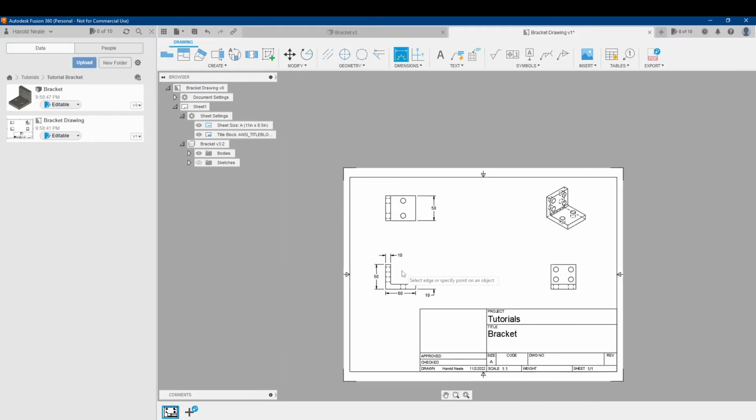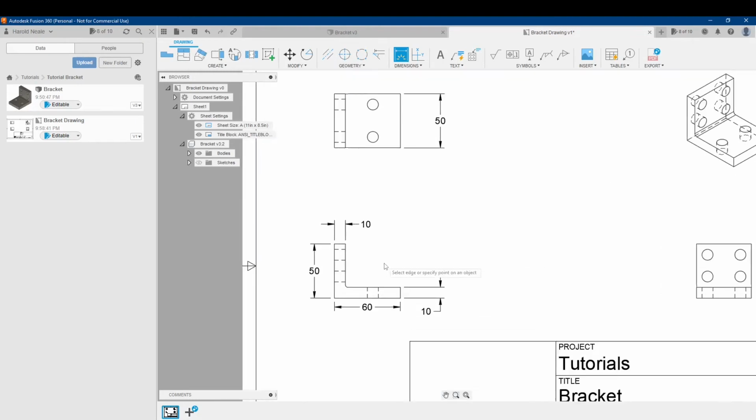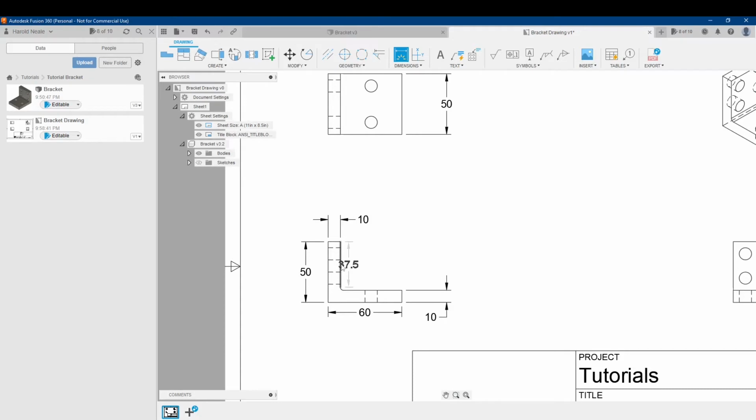We'll want to, let's see, where else do we want to dimension? Should probably dimension that right now. So here's another dilemma that you might run into as you're dimensioning things. You should not have any dimension lines cross each other. Otherwise, your drawing could get really confusing. If you cross lines, they're harder to follow where the dimensions are. I'm guilty of this when I'm doing just quick drawings on a notepad, where I can get myself easily confused, whereas when you're doing this in an Autodesk product, I feel like it's a little easier for someone to figure out when that's going to be an issue.